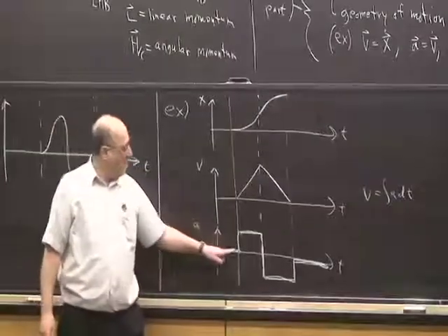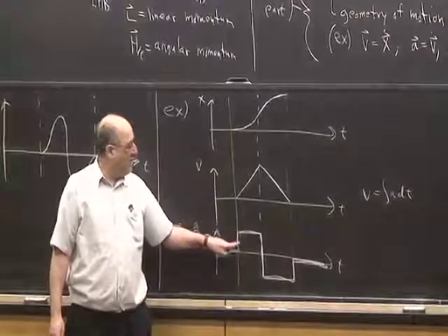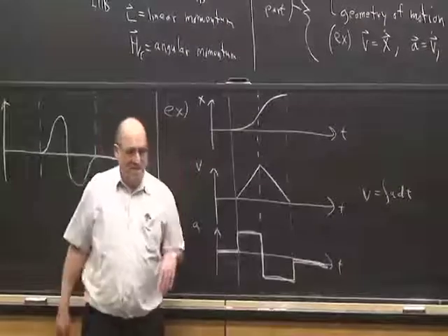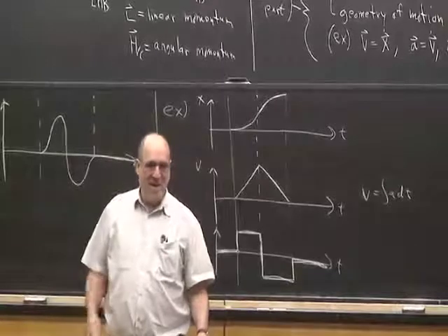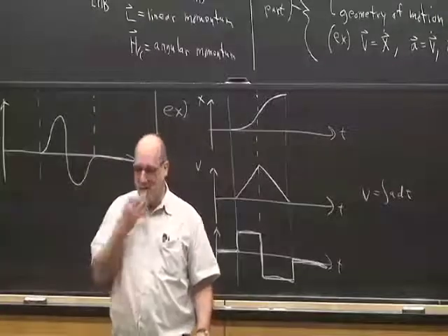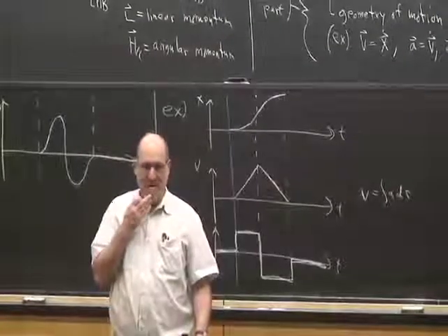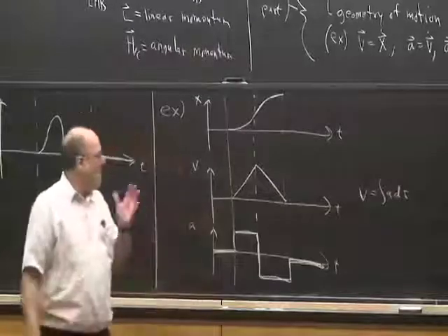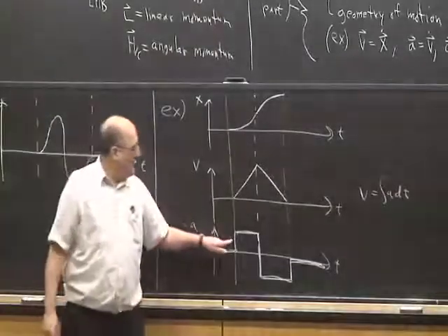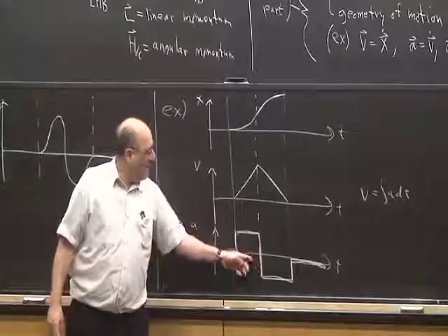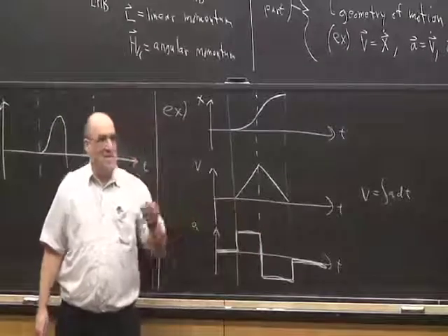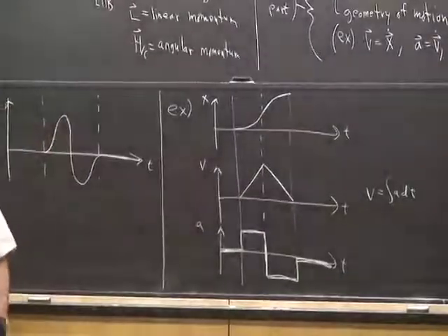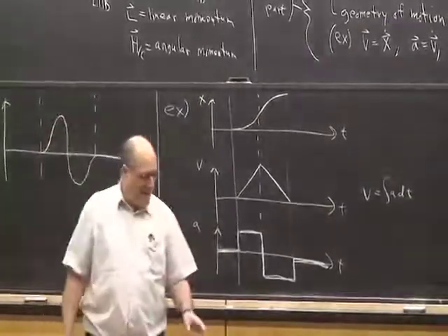If you move things in this non-smooth way, so force is discontinuous, it feels bad, it makes things rattle around, and it's a subtle issue why that's true. If you wait a while or talk to me after class, we can talk about that. But basically it has to do with the fact that if there is a discontinuity in the force in some part of the system, if there's some little bit of play somewhere, it tends to cause parts to bang against each other.